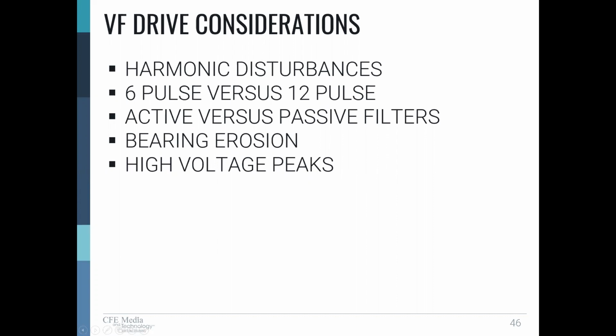And you can get high voltage peaks, which will damage the motor windings and actually damage the branch circuit conductors if it's a long distance between the motor and the VFD. There's a way to mitigate that. Again, that's more cost, which is to put inductors between the VFD and the motor.